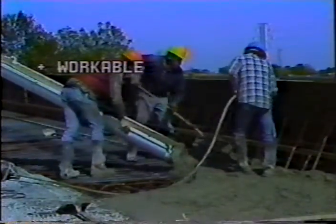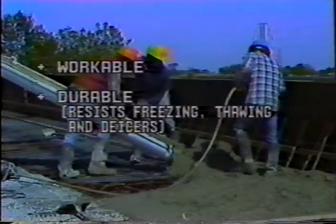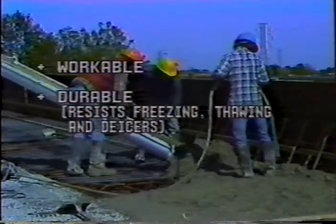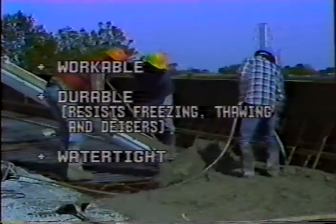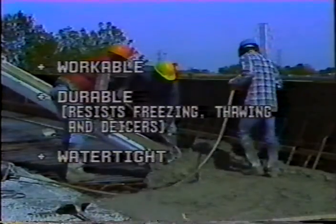An air-entraining cement or admixture produces billions of microscopic air bubbles throughout the concrete. This makes the concrete more workable, more durable, because it resists the effects of freezing, thawing, and de-icers, and more watertight. And it can be just as strong as non-air-entrained concrete. In Washington, the specifications call for an air content of 5% by volume and accept results of from 1.5% below that to 1.5% above. In other words, 3.5 to 6.5%.